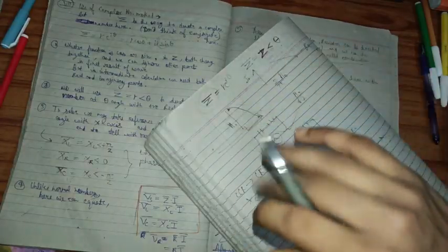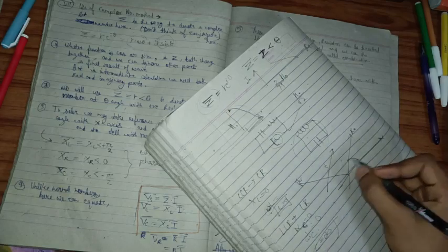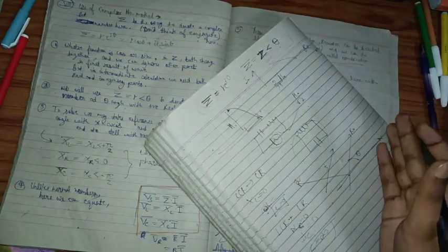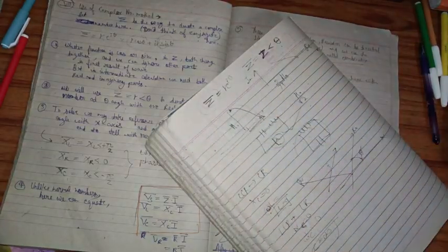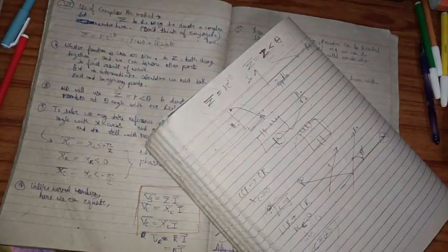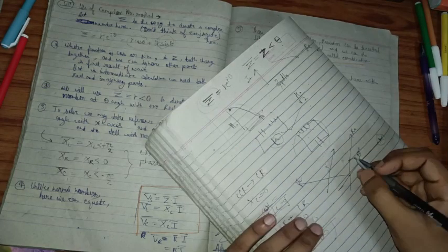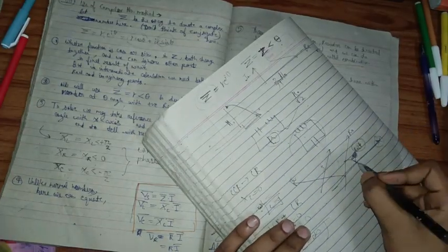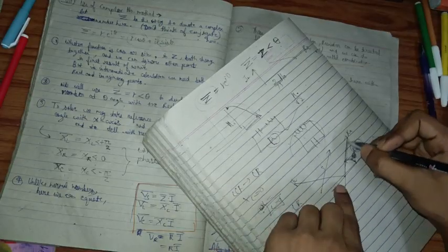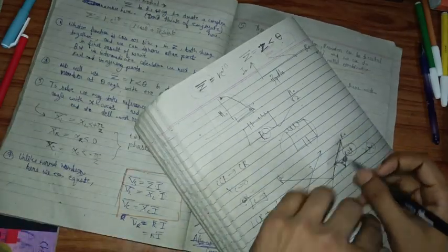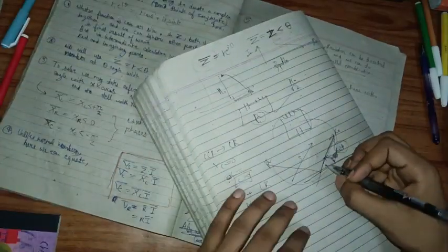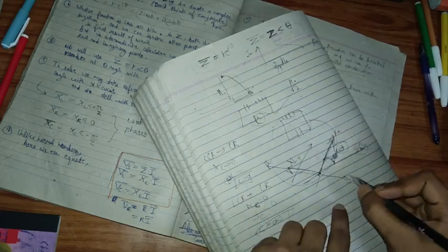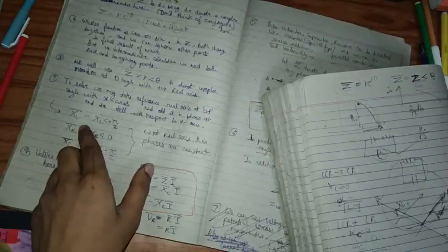And in general we solve the problem with respect to the omega t angle reference. We take a reference of omega t, the real axis lies at this angle with the x-axis, and we solve the problem in this frame. The resistance is always along this real axis, and the XL is along this direction, and XC is taken along this direction. XL is always at pi by 2 phase more with respect to this real axis. With respect to the reference frame, XL will always be pi by 2 phase ahead, and these resistances and reactances are also treated as vectors in the complex number method.